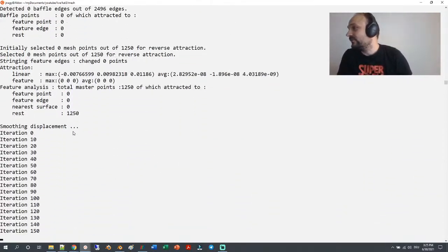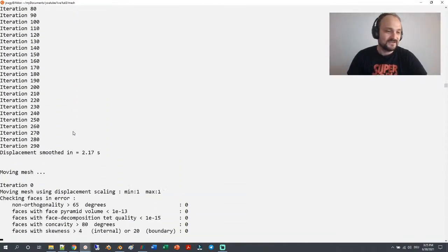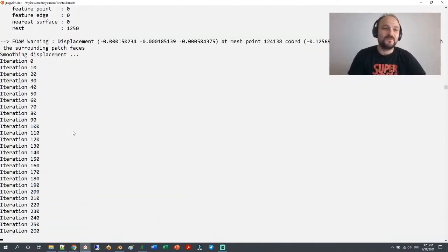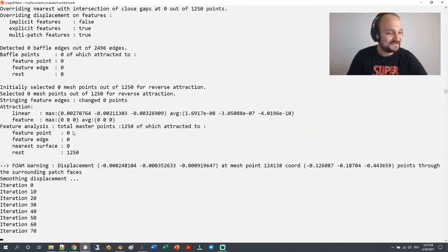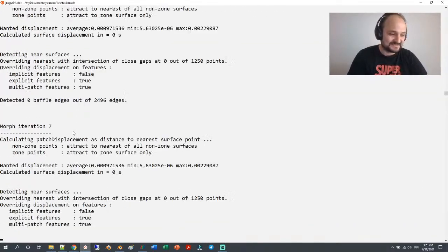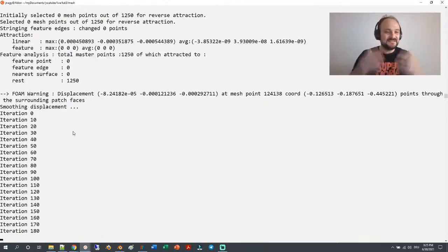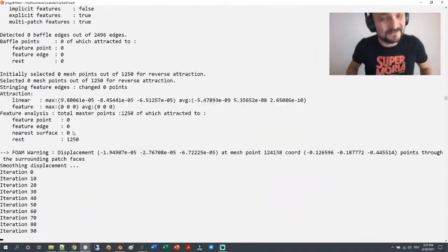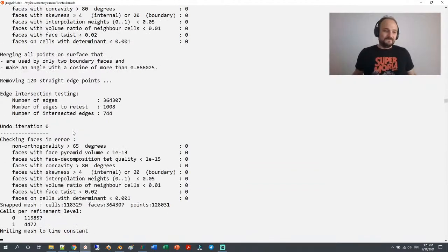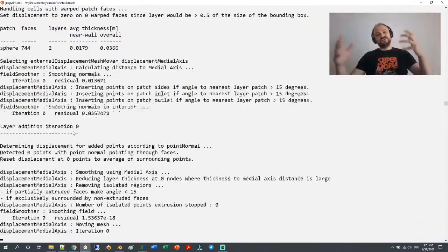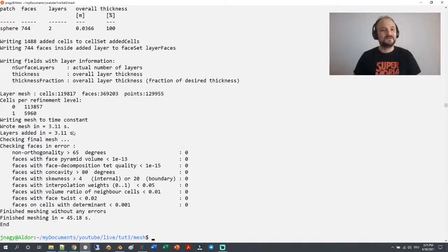Hi Lovelyette, I hope I pronounced it correctly, otherwise I'm really sorry. Do you not worry about Courant number during the meshing stage? I always worry about the Courant number, but after 12 years of CFD or even more, you just get hardened, and you see that the Courant number is quite similar to the y plus value, so usually you only know once you start the simulation where you end up.